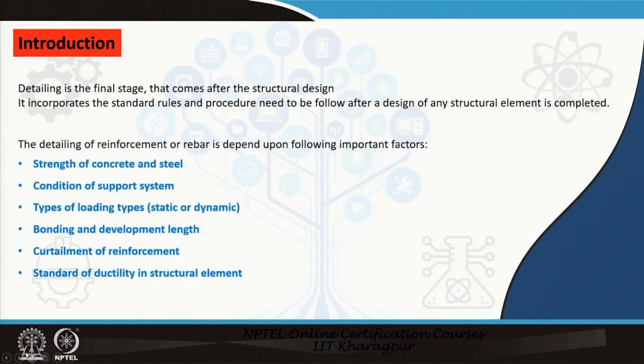The detailing of the reinforcement or the rebar depends upon the following important factors. It may vary even for the same design or the same type of loading. One is the strength of concrete and steel, because with changes in strength, the detailing will vary. The condition of the support system, because as you know, the supports are sometimes largely apart, sometimes very close by.